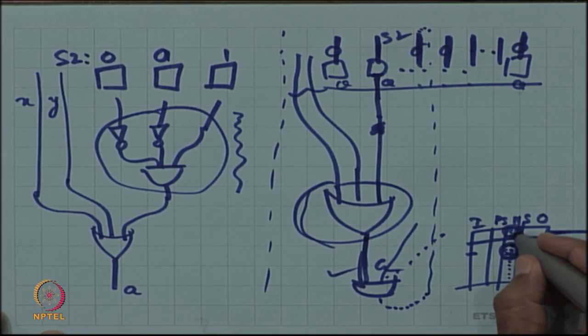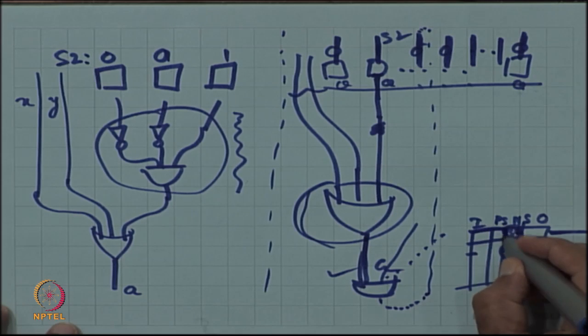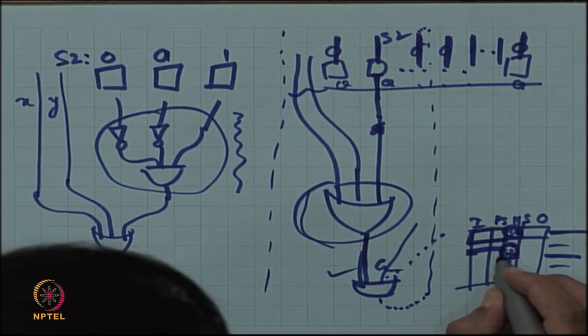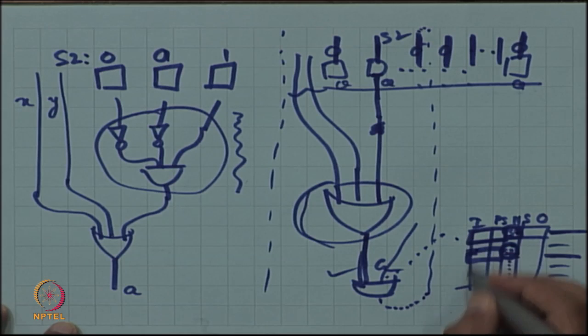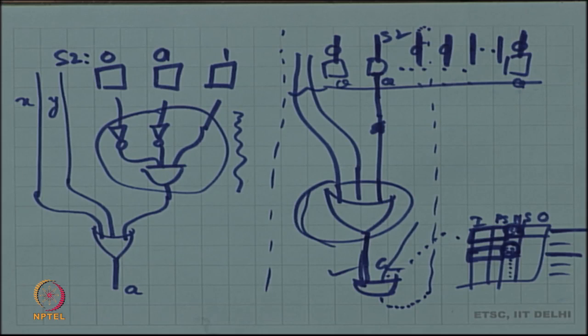So, if I have S3 is there, then I would pick up all of that. So, that logic is picked up, this logic is picked up, and so correspondingly I would build something and I would send that to the respective input of the flip flop. Now, inputs have to be sent to 7 different flip flops, as opposed to earlier I had to send inputs to 3 different flip flops.